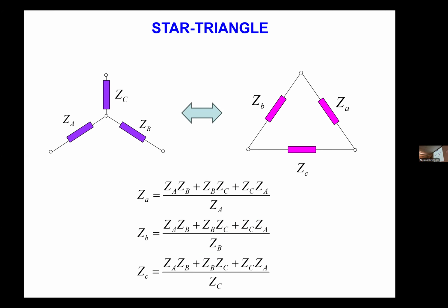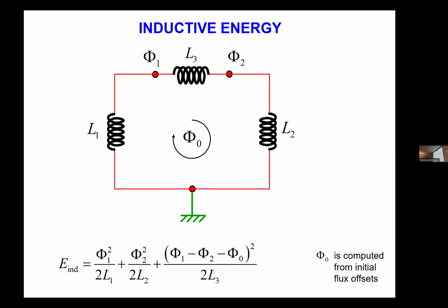transformation. So in circuit theory, when you have three elements with three different impedances, which meet at a point, you can reconfigure this circuit and find an equivalent circuit which has the same three external nodes, but in this way you suppress this internal node, and by applying this formula, you can go from one circuit to another, and that means that you see my circuit is actually equivalent to this new circuit.